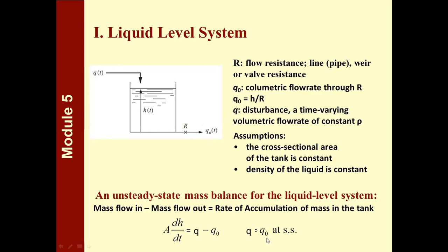Why? It's because at steady state, we expect that the volume and the level as well of the liquid inside the tank will be kept constant. Now, if these two are not equal, then there would come a time that the level of the liquid inside the tank will decrease up to the point that your tank will go empty, or it will overflow if the volumetric flow rate through your linear resistance is smaller in value than the volumetric flow rate of the fluid that is entering the tank.